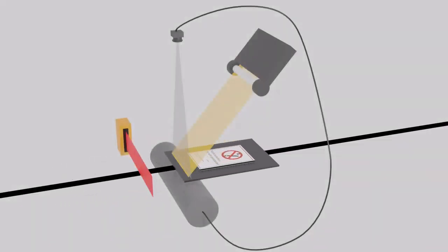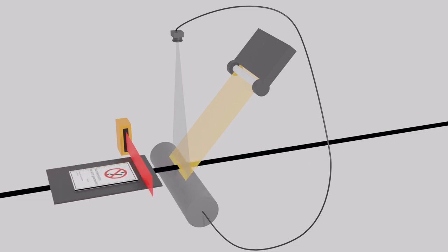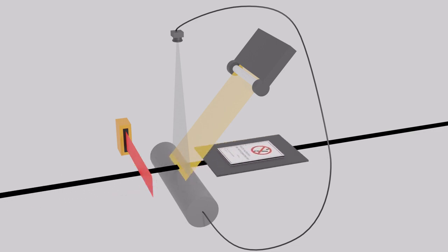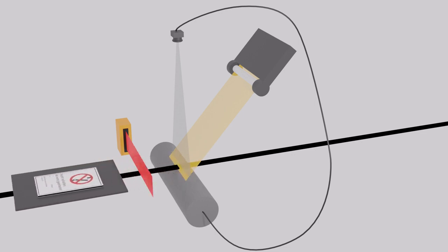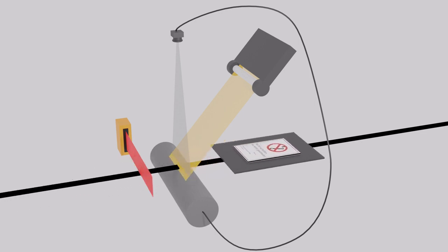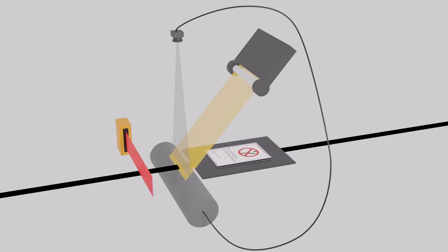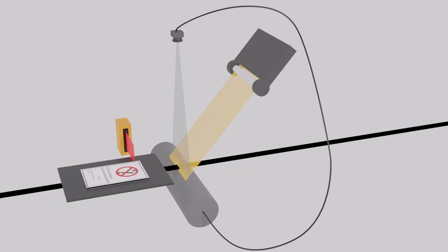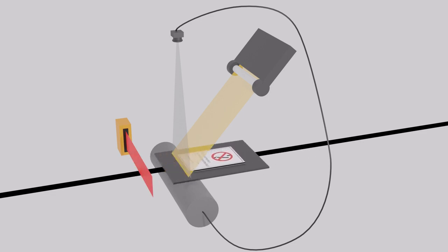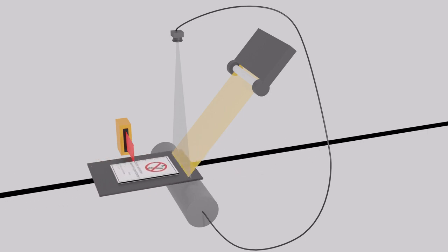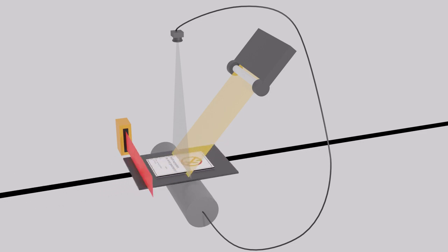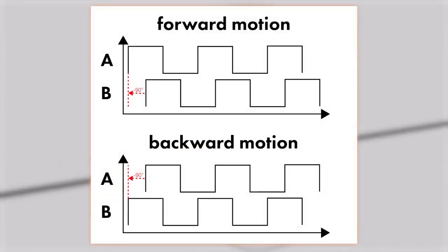The shaft encoder module allows us to use both line 1 and line 2 to determine in which direction the slide is moving. Line 1 and line 2 are set to phase A or phase B, depending on which direction should be defined as forward. To be sure whether line 1 or line 2 should be phase A or phase B, you can connect an oscilloscope with at least 2 inputs to line 1 and line 2 and visualize them simultaneously.